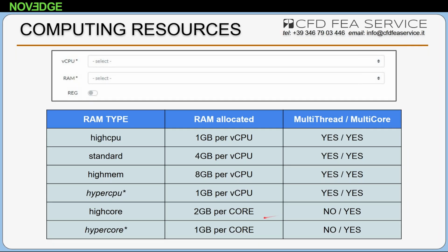For every simulation, basically, you can differentiate the amount of RAM. Every time you start a new analysis, you are also selecting the hardware where you want the analysis to be performed. You can allocate more RAM, less RAM. You can allocate hyperthread or disable hyperthreaded. Okay, and there are several configurations. Here they are reported. Like you have normal hardware or premium hardware, depending if you want AMD EPYC Milan or you want the Emerald Rapids we saw before, the Intel Emerald Rapids processor, which is about 2 times faster compared to the AMD EPYC Milan.